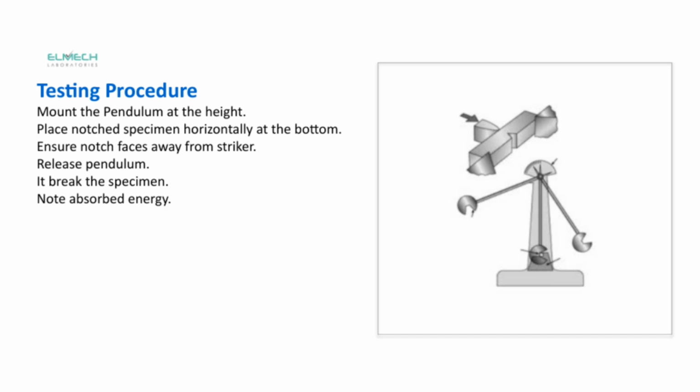Next, release the pendulum freely. Gravity will do the work. When it swings and hits the specimen, it will break or fracture the material at the notch. After the fracture, you'll want to carefully note the energy absorbed during this process.